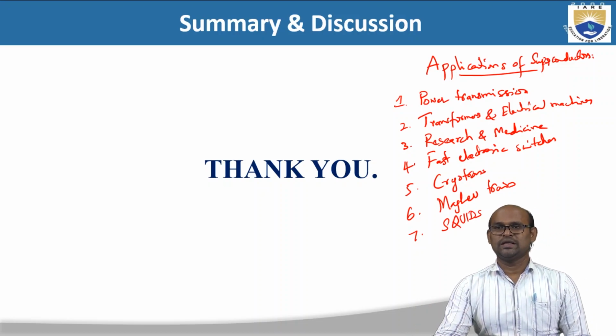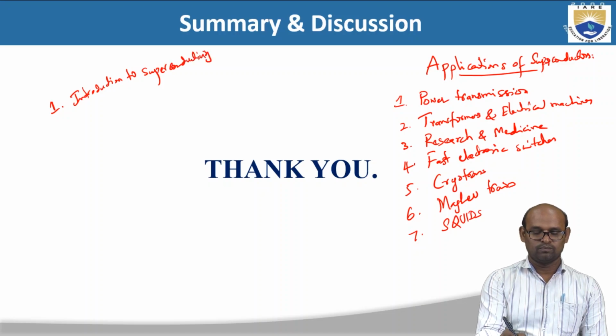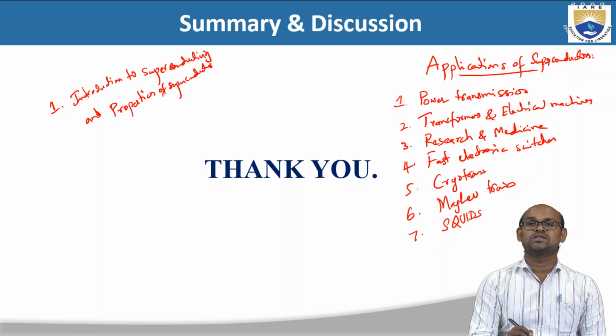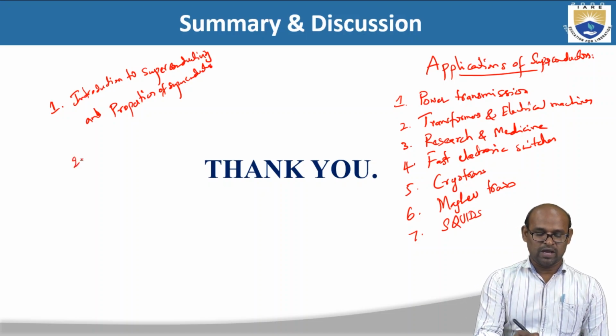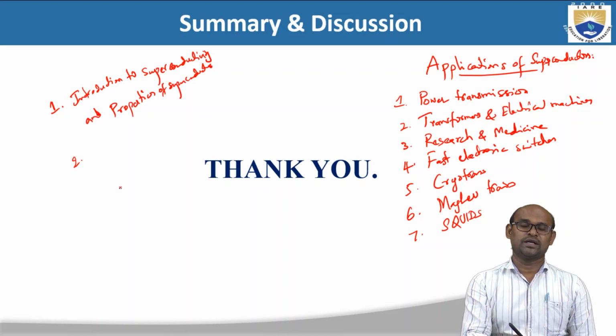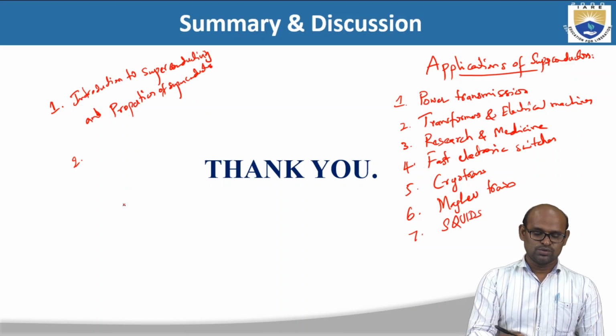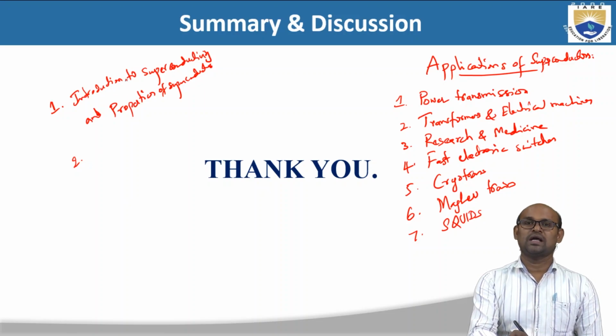In this module on superconducting materials, I started with the first presentation, an introduction to superconductivity, and also discussed the properties of superconductors. I discussed what is superconductivity and what is a superconductor, and then the properties of superconductors: zero resistance and critical temperature, critical magnetic fields, the diamagnetic property which is also called the Meissner effect, persistent current, and so on. That I discussed in the first presentation on superconductors.